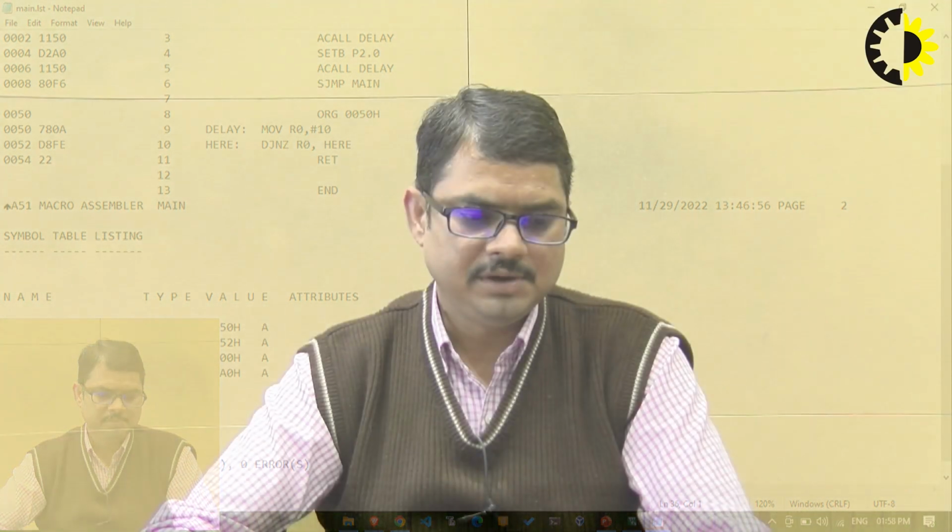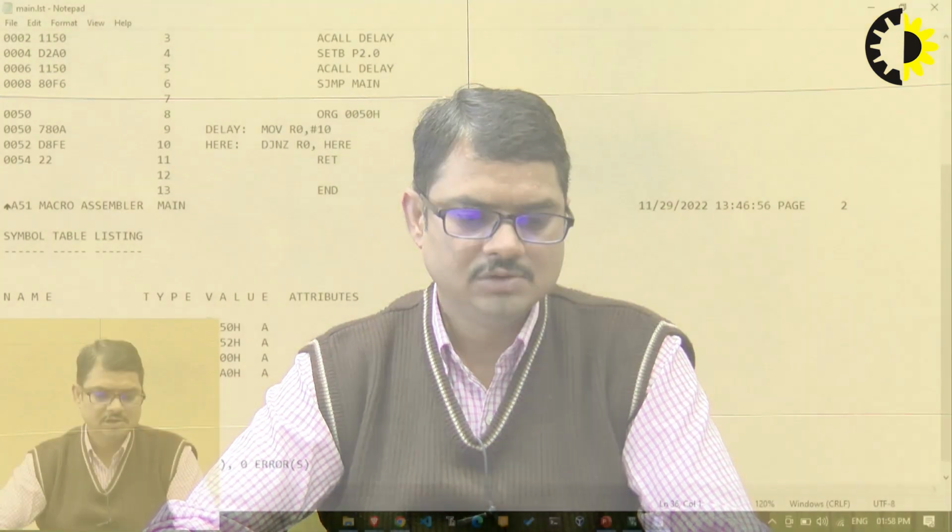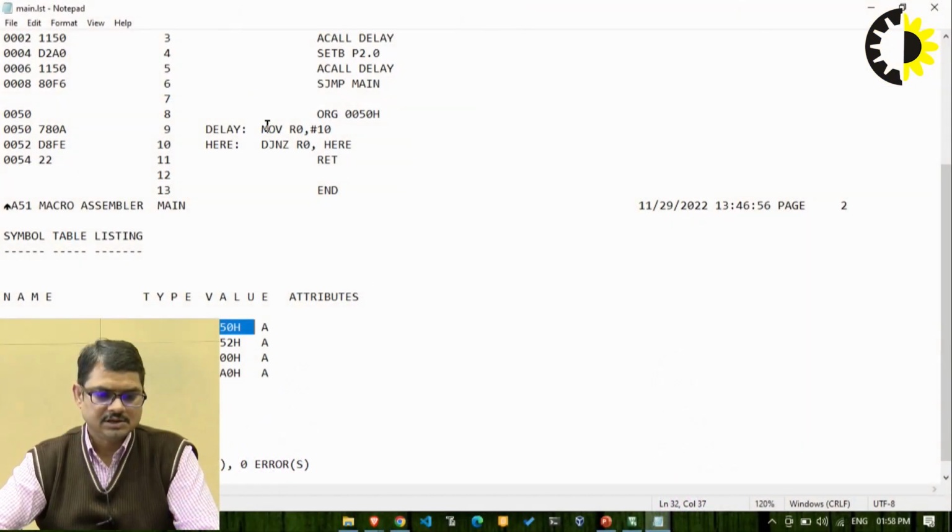So we know that main has the memory location 0000H, that's good, and we know that at memory location 50 there is a label of delay, so delay location is 50H, and this instruction takes 2 bytes, MOV R0, #10, so 2 bytes have been consumed, 50 and 51.